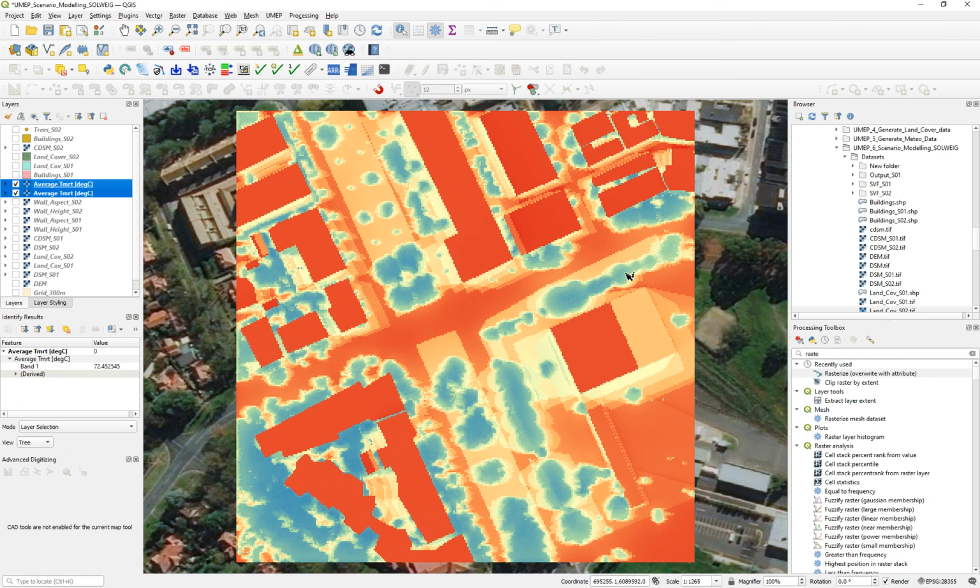And that's why the process was a bit tedious, but you notice that we need to build all the elements in a logical way. So you need to design a workflow first, starting with the trees, adding the building, sorry, and then locating green walls, locating green roofs, locating the trees. Then you start generating the different data set inputs for the second scenario that you needed, and then test different options, and you will see that the results of improvement in the outdoor thermal comfort make a lot of sense.